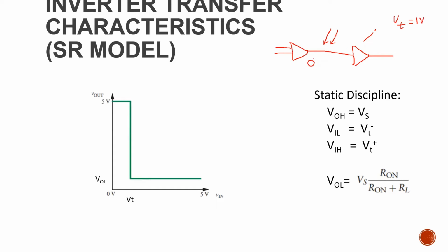Now here, because of the noise, 1 volt, this second driven element is receiving a 1 volt signal. Then what does this driven element think? Okay, I received logic 1, I have to send logic 1, like that it will think. But actually the driver element sent logic 0, right?